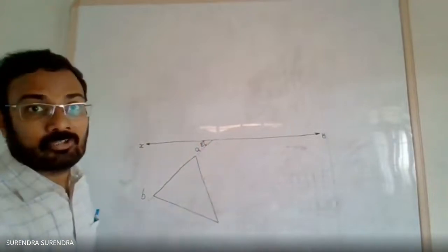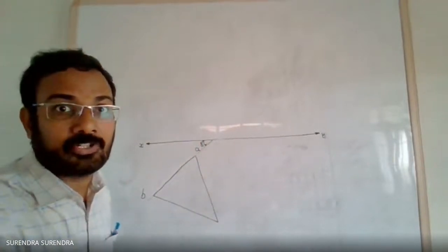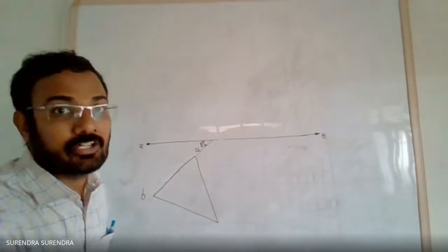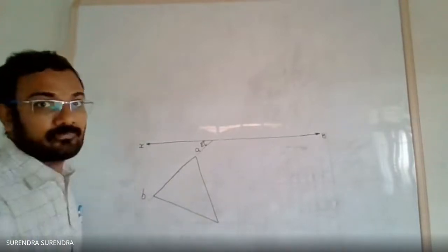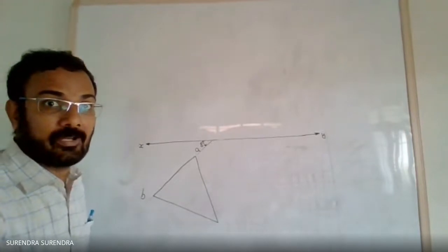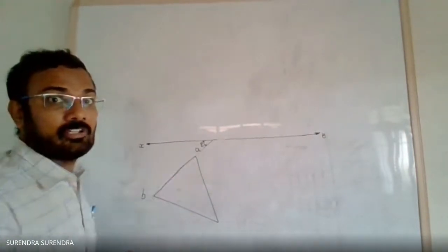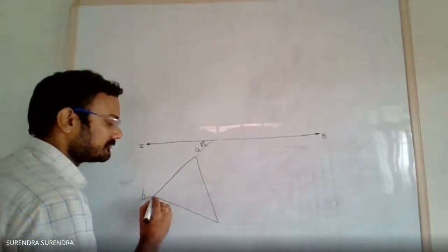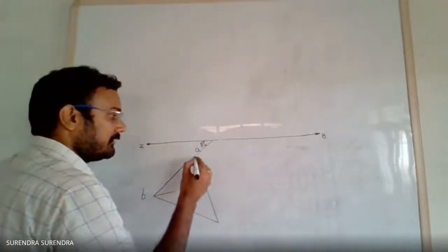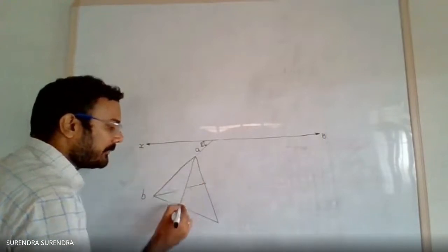With one of the base edges inclined at 40 degrees to the reference line XY. Now, as it is in the shape of a pyramid, we should join all the base corners to the apex. Join each corner to the opposite side midpoint.